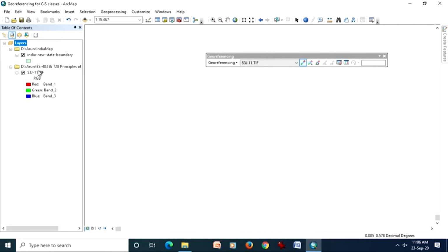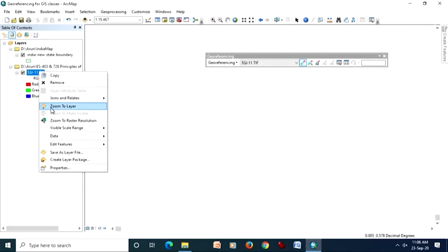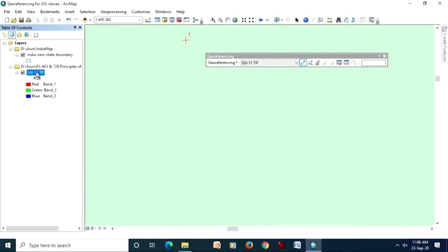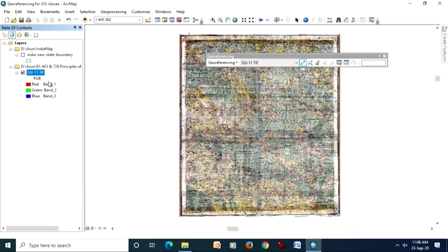For the time being the image has disappeared, because of rubber sheeting. Now, at that location in the map of India or on the globe, that one control point has pulled that point. So, no problem, we will bring back that point again, and that is here now. Next thing we should do, like the shoemaker analogy I gave, is go to the diagonally opposite corner to collect another GCP, another control point.